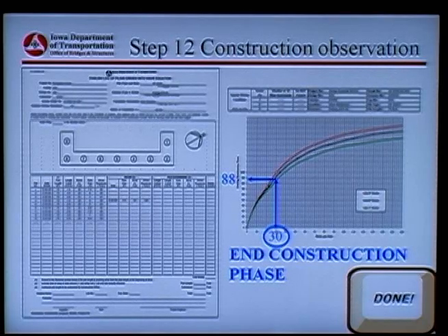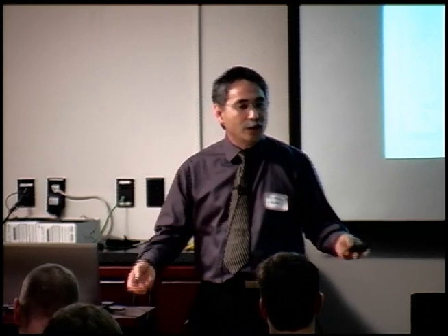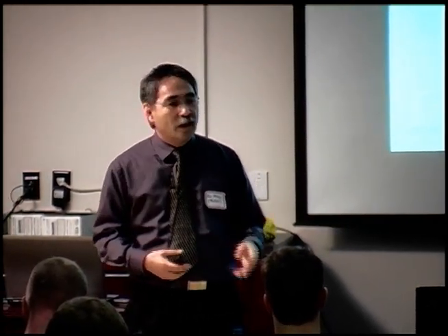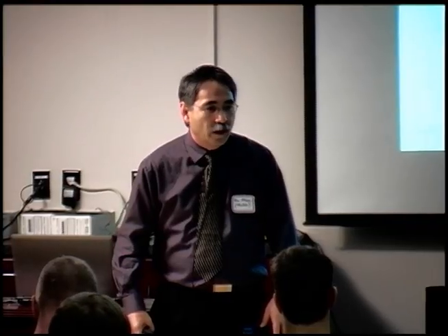Does that make sense? Everybody okay with that? Are you comfortable with the idea of accepting a pile below what the structural engineer required, because of the setup, right? You should say, no, I'm not comfortable with that. I don't believe in lip service. I like to touch and feel, and so we know that. How do you get that comfort? Retap it a day later.